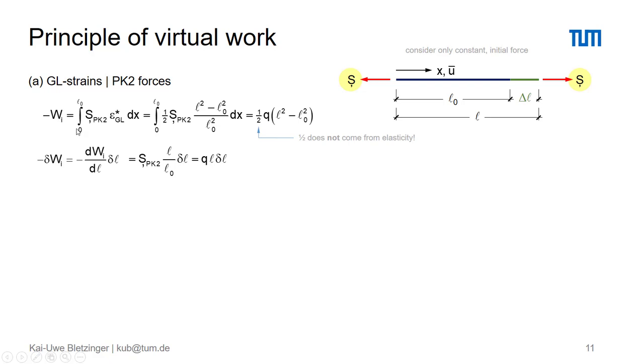So we have to integrate along the undeformed geometry the product of the constantly given Piola-Kirchhoff forces of second kind, and the Green-Lagrange strain referring to the final state of equilibrium, if we just refer to these previous seminars. Substituting our expression for the Green-Lagrange strain, 1/2 times the difference of the length squared before and after deformation, I just write this 1/2 here in front.